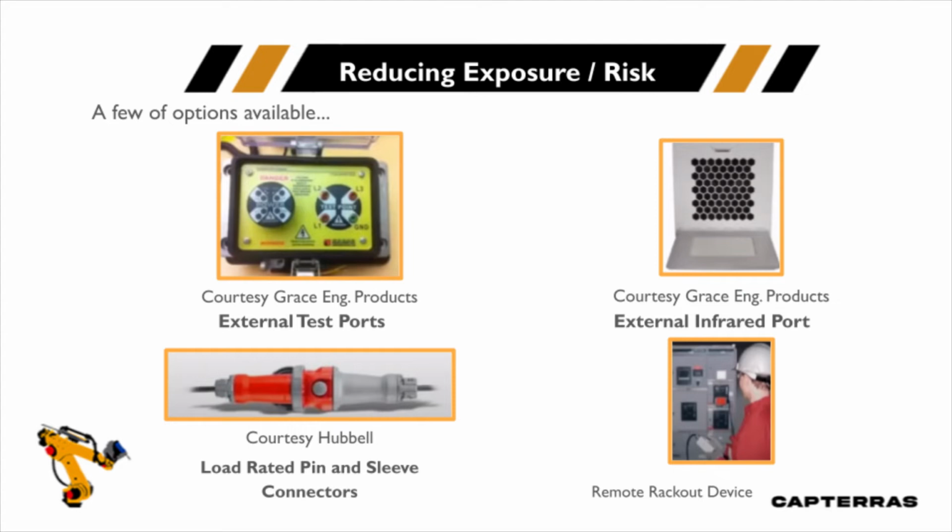So we would verify that we have voltage, shut it off, verify the voltage went away, and then we probably would be able to open the cabinet, depending on the type of cabinet and so forth. And again, I can't say this in a blanket statement for all equipment, but this is one of the ways to help avoid even having to put the PPE on to verify zero energy: having a disconnect in a separate cabinet or enclosure with a test port.